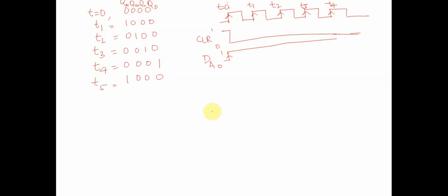Now what will be the QA, right? QA, if initially it was 0, at time t1, it will get a value. Okay, so basically what would happen over here is, let's assume this is a time t0, everything was 0. But what we did over here is we applied this particular d value just before it, right? So let's look at our particular equation over here. QA at time t equal to 0, just before the clock edge, would be 0.